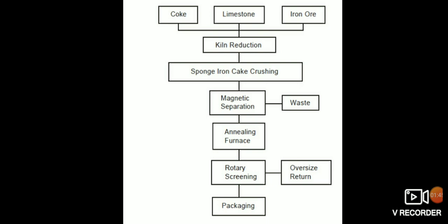The ore is ground to a particle size distribution determined by the desired iron powder. The ore powder is placed in the center of cylindrical ceramic containers, saggers made of silicon carbide, surrounded on the outside by a concentric layer of a mixture of coke and limestone.